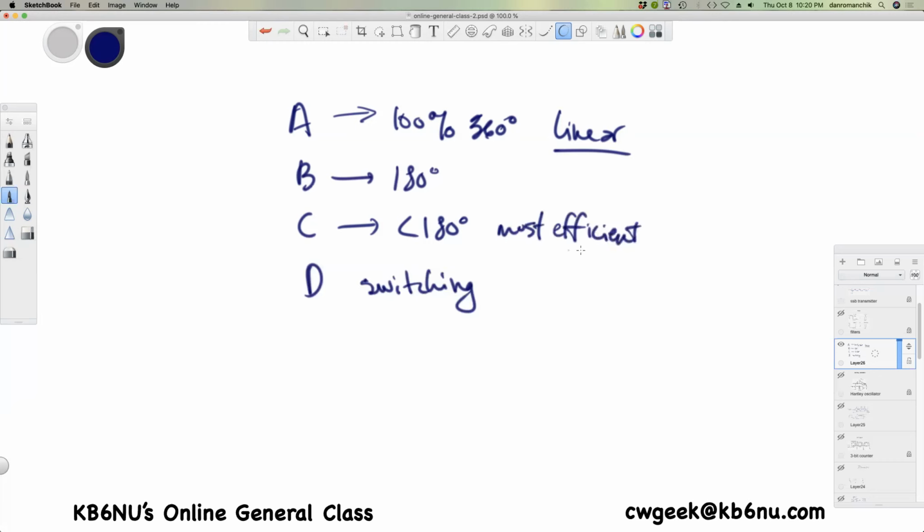And we can use this for FM transmitters because we don't care about the waveform so much. All we care about is the frequency. And this will preserve the frequency, if not the input waveform. So this is the type of amplifier we often use for FM. Question, which of these classes of amplifiers has the highest efficiency?